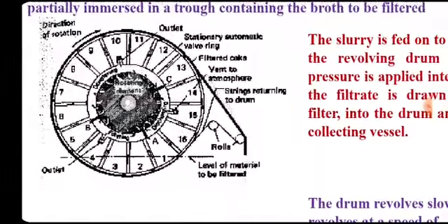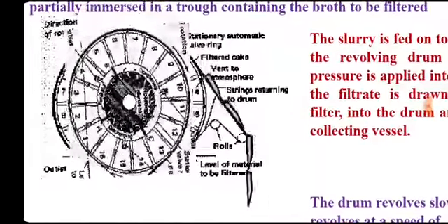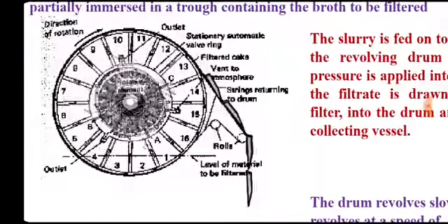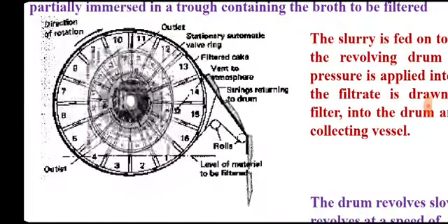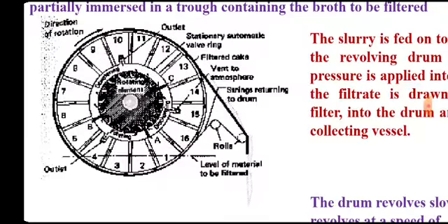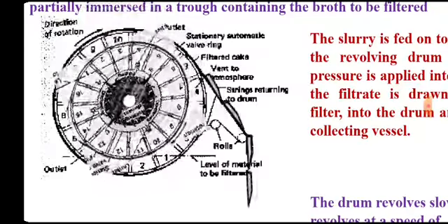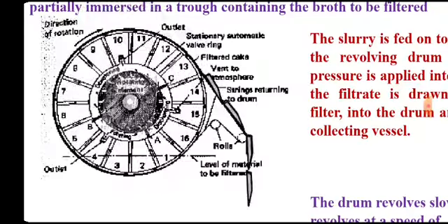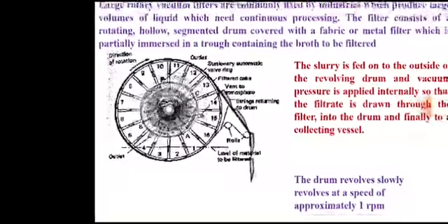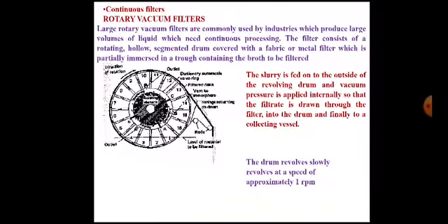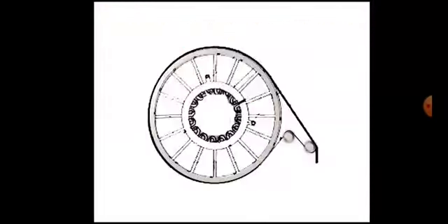So what is shown in this diagram is the insoluble impurities which remain outside this drum are continuously getting discharged through this string. It is called a string discharge. So the rolls are continuously rotating, and filter cake or the impurities are getting discharged.